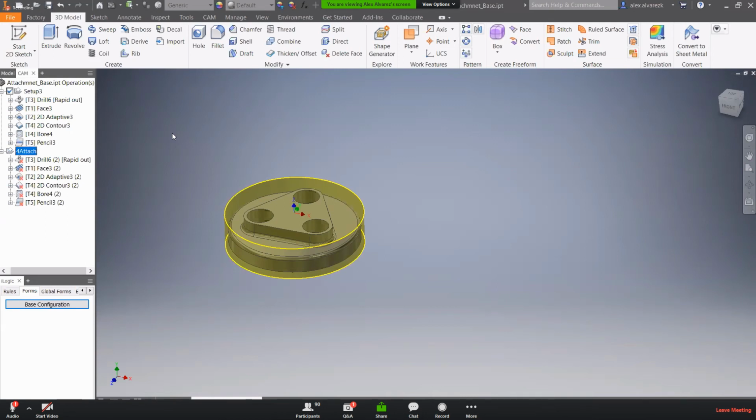So that's where you want to start taking a look into 3D toolpaths. I'm not going to get into the whole background behind 2D and 3D, but really the gist behind 3D toolpaths is that it's driven specifically off of model geometry, right? So if you're driving a toolpath from model geometry, that means that this model can change between 2, 3, 4 different attachments, and it's not going to care, right? As long as the geometry is there and it's a fine geometry, then it's going to be able to generate some sort of toolpath.